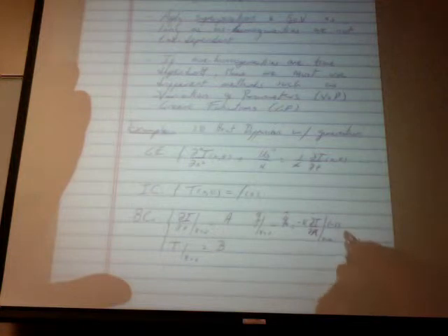Well, this comes from saying that q at x equals 0 is equal to q0, which is equal to minus k dT/dn, minus k dT/dx at x equals 0 times minus 1. So therefore a is equal to q0 divided by k.